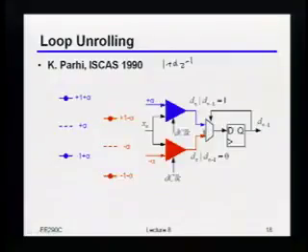Okay, so again, just like with a normal DFE, this is completely recursive, right? Because notice I need to know what the previous bit was to select the current correct bit. But that's no different than what we were doing in the analog domain as well. Okay? So the trick here is that now I've removed the analog settling time from the picture because I'm just statically selecting between these 2 coefficients that I'm just statically going to set. Okay? So now I've pushed the timing path to be purely this digital loop that may actually be much easier for me to get closed. Okay? Does this make sense to people?